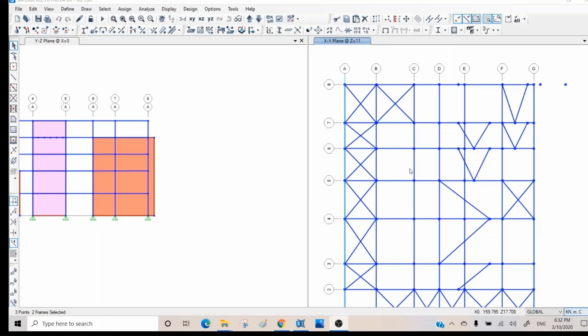The other item I want to discuss is adding a grid line. Sometimes you want to add a secondary grid line based on some key joints that you created in the model, and you want to see them in elevation. The grid line created based on a joint is always secondary, not primary. Primary joints have a grid number, but secondary ones do not. You can edit it later in the edit grid data if you want.